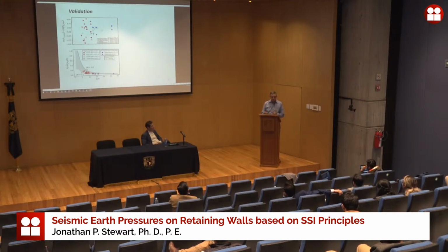There are other times we make models where it's actually good, at least in my opinion, to have bias. These are when you simplify a more complicated problem to a simpler one so that you can get an answer quickly. If you're going to take a shortcut, there should be a penalty. You should be conservative. You should be having thicker walls and things like that. You should never have a simplified method that is unconservative.